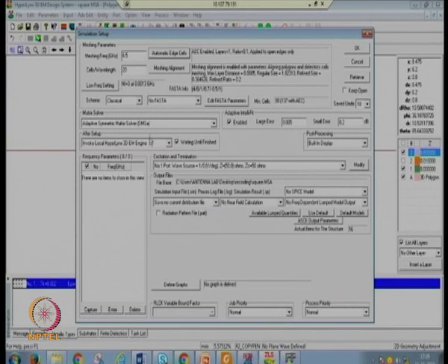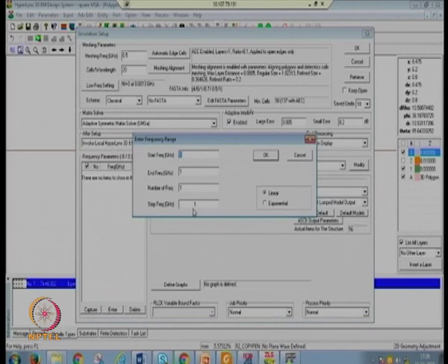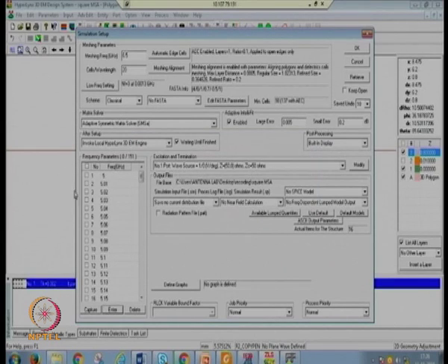This is a scheme which runs in the background of this particular software. It uses multiple CPUs to simulate the antennas. The next part is we need to define the frequency. Here, let us take it from 5, give the start frequency, then end frequency, and the number of frequency points. You need to give sufficient frequency points so that it should be able to calculate results properly by picking the frequency points. Let us take 151. Corresponding to this, all the frequency points are given.